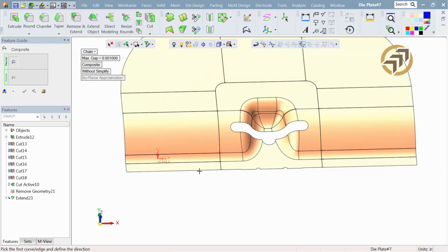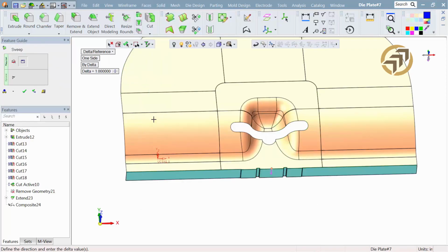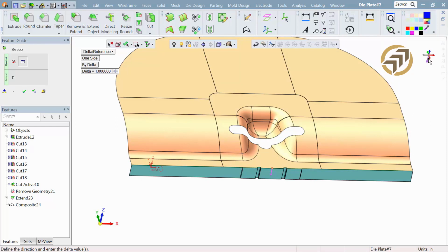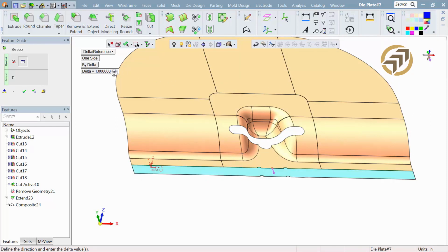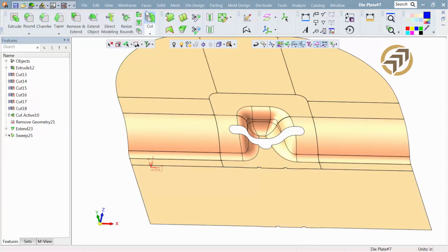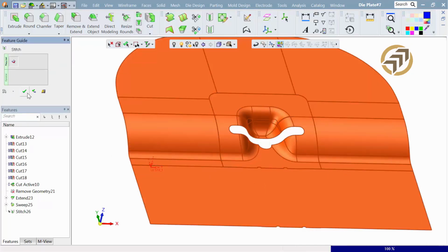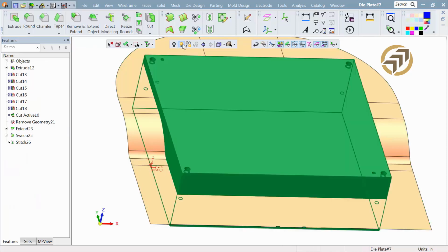Now let's do along this other edge. We'll simply chain from side to side. You notice there's a little notch left in there. As I sweep that face out, which is basically like a big ruled face, you notice it doesn't care about the notch. So I just simply make it big enough that the notch is off the side of the block, it becomes irrelevant. And you even see it do that with the areas that are undercut, if you can imagine that. So basically it's giving me a flat, planar face as my solution.